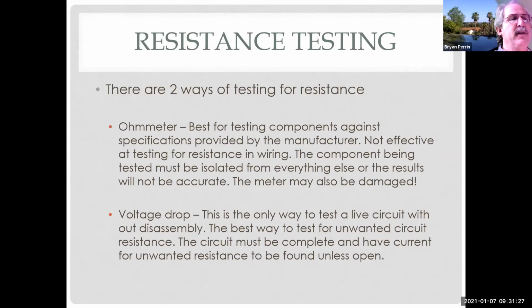Voltage drop is the best way to test a live circuit without disassembly. This allows me to test something without taking anything apart. Keep in mind, anytime we take something apart, I might damage something. I might accidentally fix it and have no idea what I did. I may break something else or cause a new problem. So the circuit must be complete and have current running through it for the unwanted resistance to be found, unless it's open, in which case I will pick up that I have an instant problem.